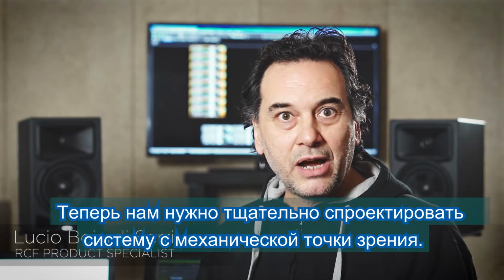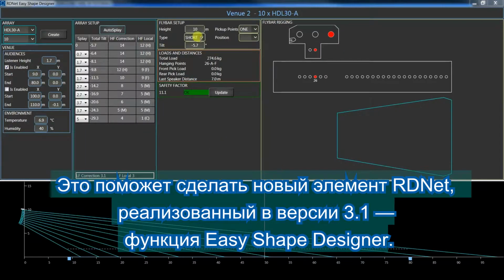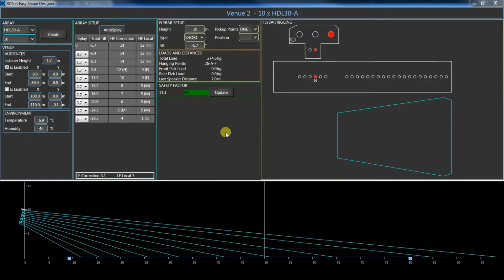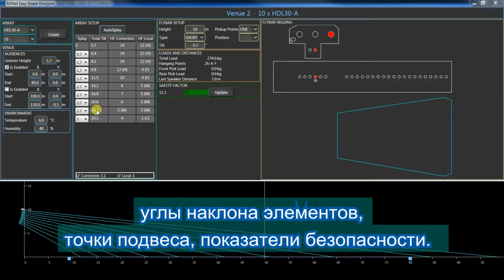Hello again! Now we have to design properly our system from the mechanical point of view. To do it, Easy Shape Designer is now available as a new feature of RDNet 3.1. It allows to design and get in few clicks all the data we'll need to set up the clusters, angles, pickup points and cluster safety factor as well.